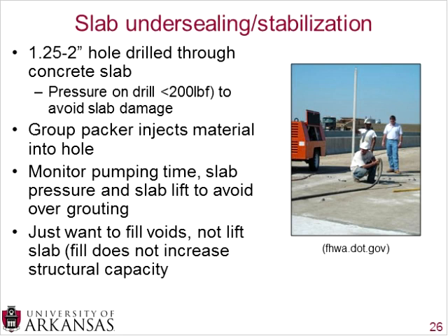It is very important to remember, when you are undersealing or stabilizing, you are filling your voids, you're not lifting the slab up. And this fill doesn't increase your structural capacity either. It's a replacement of material that has gone away and created that void. So you're not increasing structural capacity, you're simply putting the structural capacity back to what it was before.